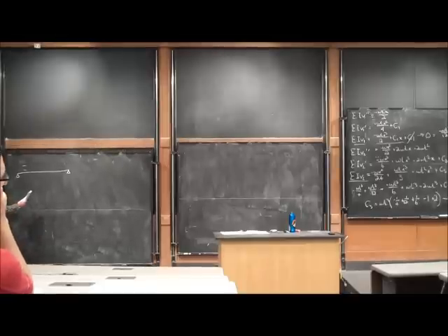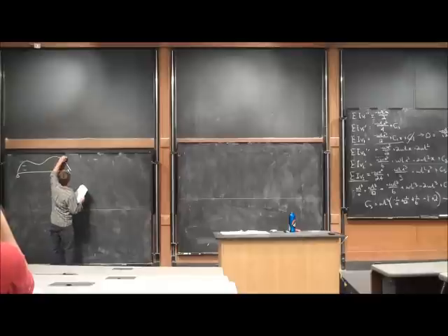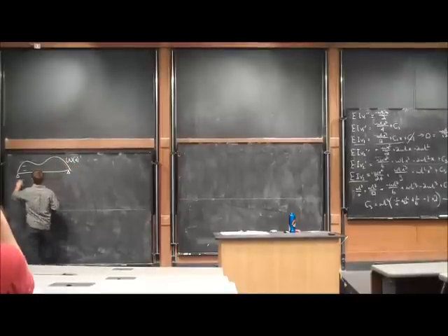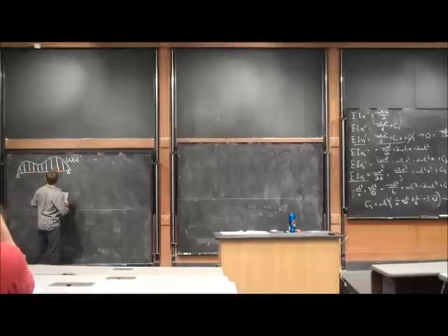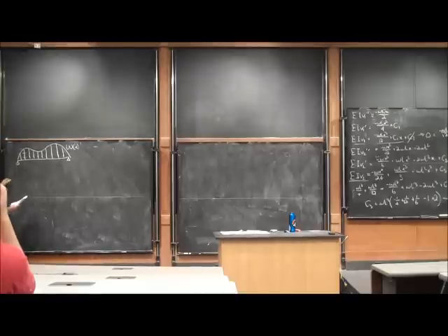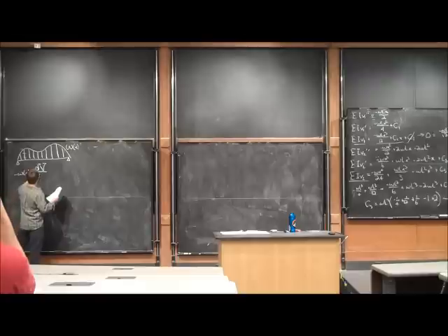Okay, so if we have some loading equation that we don't know what it is, or we know what it is, but it's not something that's easy to examine. We have some loading function w of x. We can do the same sort of thing if we recall from when we were doing moment and shear diagrams that negative w of x was equal to the derivative of our shear, capital V, with respect to x.